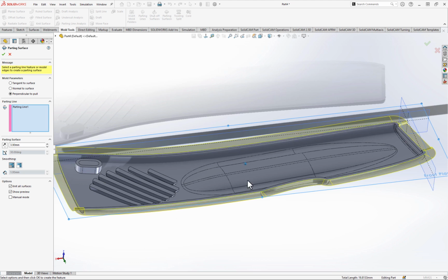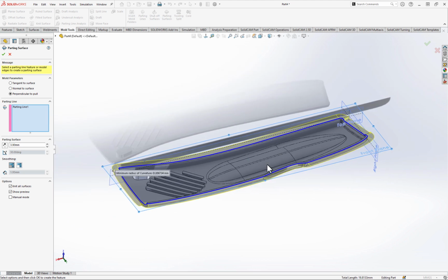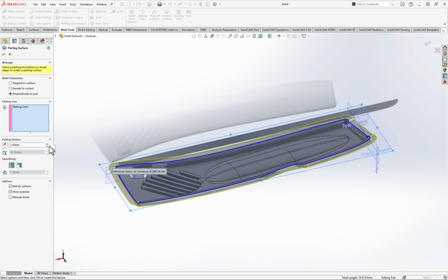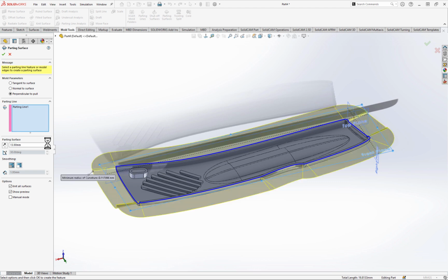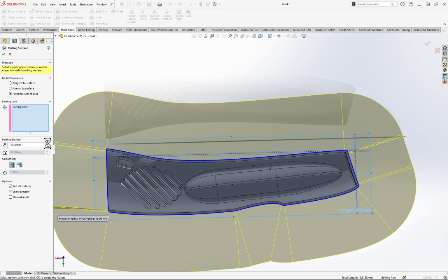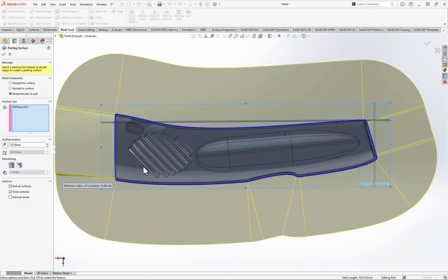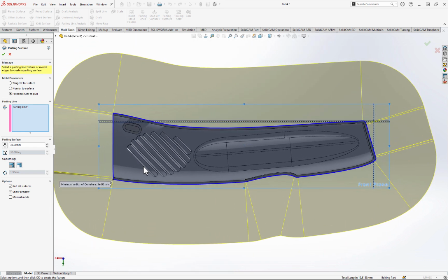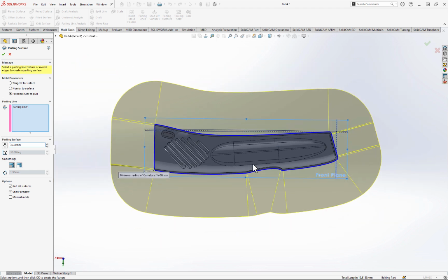And this projected surface is going to act like a cutting tool to split one block of material into the core and the cavity. So we need to project this outwards quite a long way in order for it to be big enough to clear our moulding tool. So again, you might have to play with these settings slightly just to get the figure that's best for you. But we'll see in the next step.